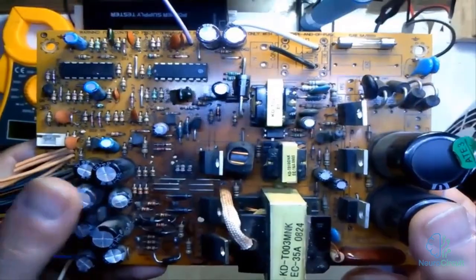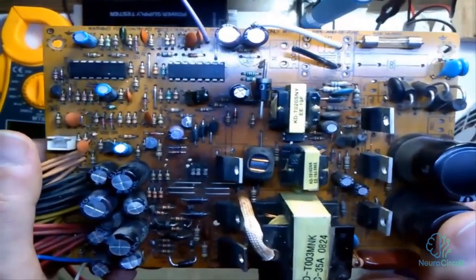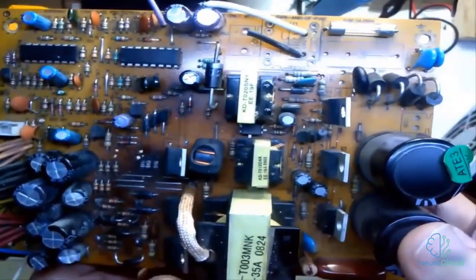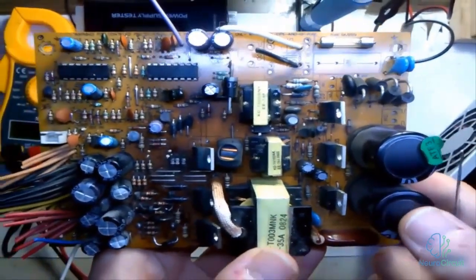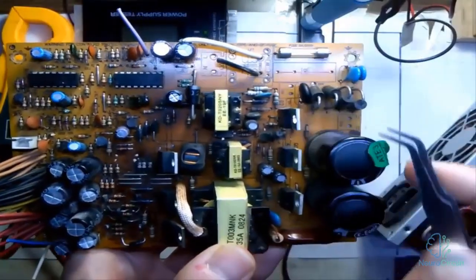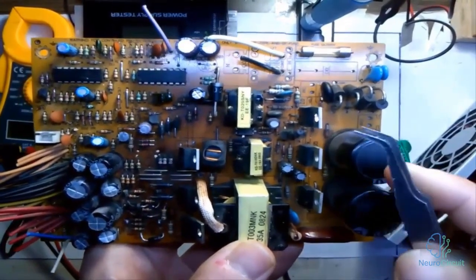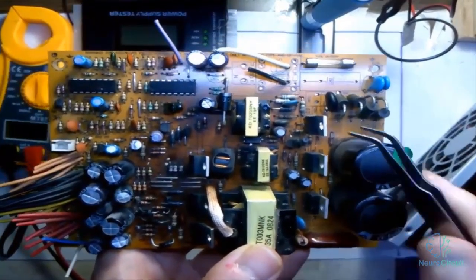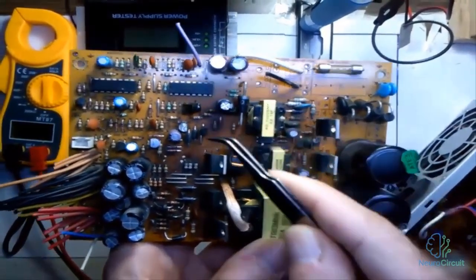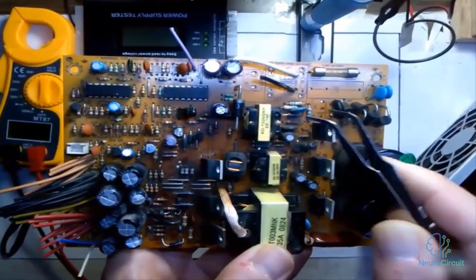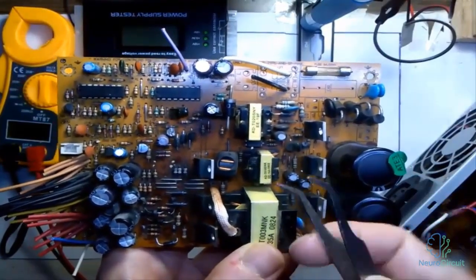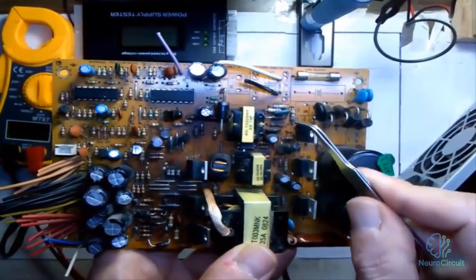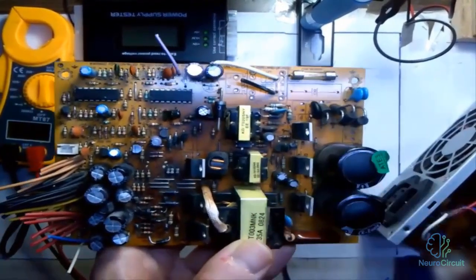These are all things you need to diagnose in a power supply, and in this training series you will learn all of them thoroughly. So if you come across a faulty power supply that, for example, doesn't turn on, you need to investigate a specific section. If you see a power supply where the standby circuit isn't working at all, how should you troubleshoot the standby circuit? There's a method for that, and you need to test a particular section. Not all sections are related. For example, a standby circuit failure has nothing to do with the output circuit or the primary circuit, so we should only test the standby circuit.